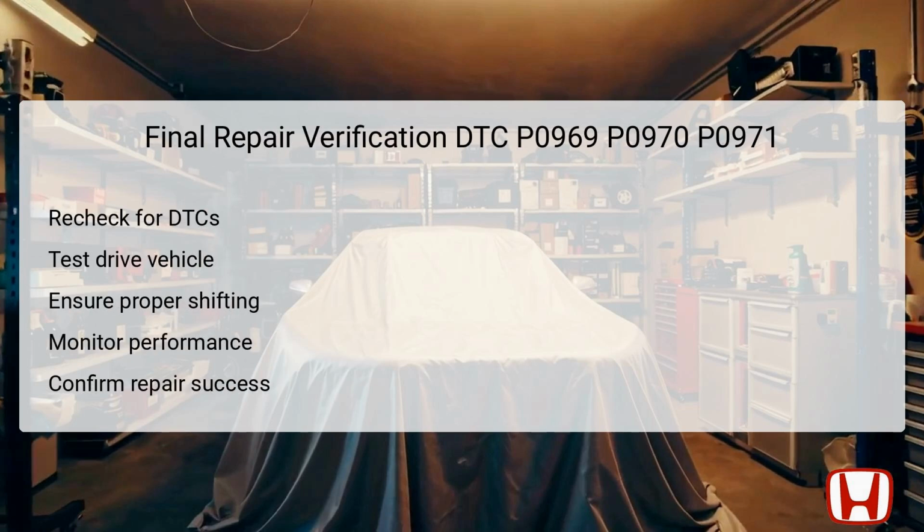After completing the troubleshooting and any necessary repairs, it is imperative to recheck for DTCs using the Honda Diagnostic System. This ensures all previously logged codes, particularly P0969, P0970, or P0971, are cleared and not returned. Conducting a test drive of the vehicle follows this.